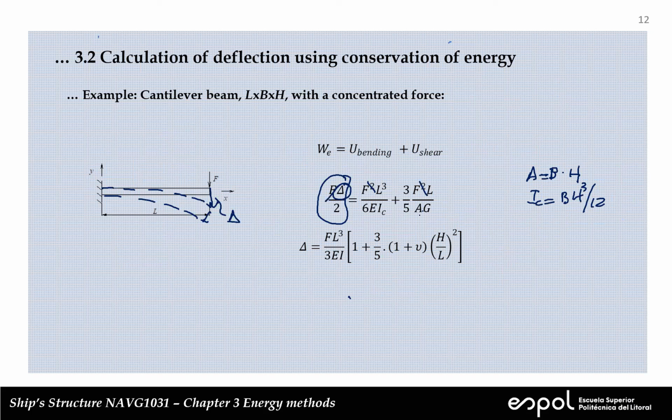So this A here was replaced like this, and we took some common terms, and that's the final expression, okay? This term here has units of force, length cubed over force over length squared, that's for E, and the inertia has units of length to the fourth. So I have 2 here and 2 here, that cancels that, F, and you get correct units.